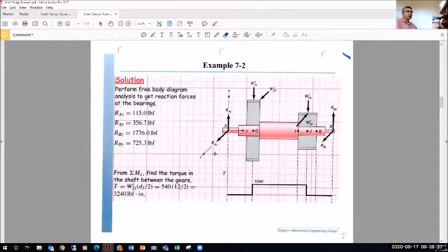Also, we have 3 equations of moment. Sum of the moment about X, which I can use here for torque equilibrium. If we know that the shaft is going at a steady speed, in this particular problem, we're not going to use this equation. So I have 2 that are left, namely sum of the moment about the Y direction and sum of the moment about the Z direction. So practically, I have 4 equations that we can use to find the 4 unknown support reaction components, RAZ, RAY, RBZ, and RBY, which I trust you can all do.